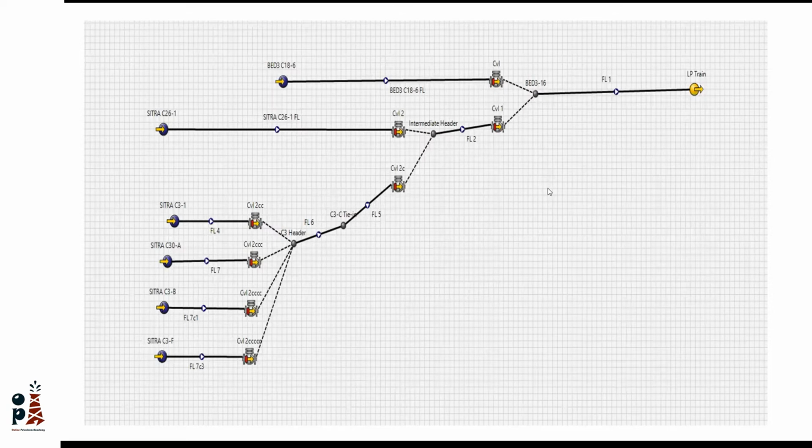All of them produce to an oil production facility, and these wells together form a network model. Each of them will affect each other by the back pressure, which is proportional to its flow rate and the pressures. This means that before putting a new well onto the network, we need to model it and model its effect on the other wells.